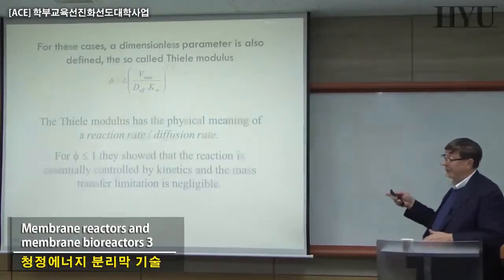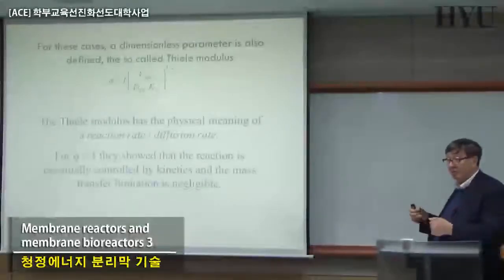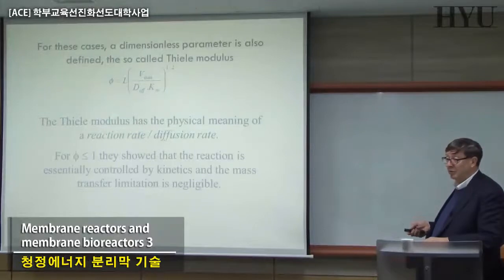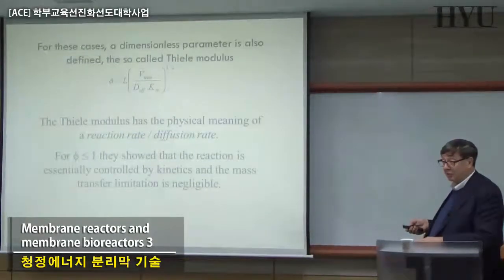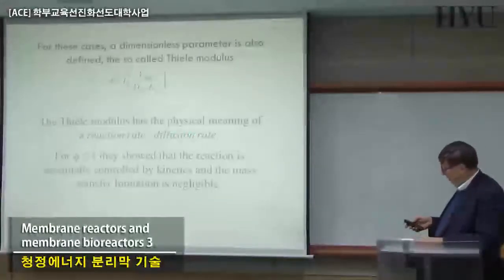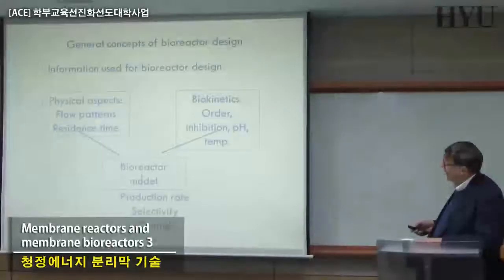So if the system is not very efficient, you can slow down the transfer of the reactant by diffusion to the active site, and you block the reaction for this. This becomes the controlling step. You can have two extreme cases, diffusion rate or reaction rate, exactly as we saw a little bit yesterday.